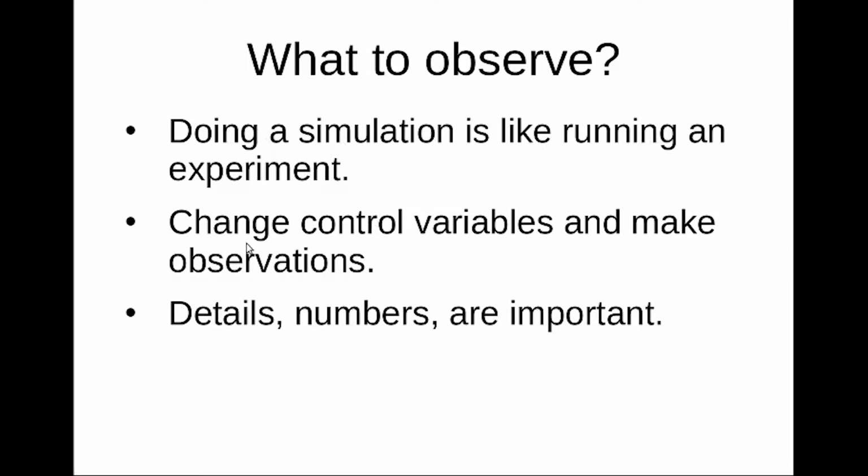So you will have to change the control variables. For example, in the previous simulation you can see that I've changed the duty ratio and studied the result. If it is a closed loop system, you can study the controller performance by introducing changes in the load or changes in the input voltage and so on, and study how the dynamics of the system evolves.